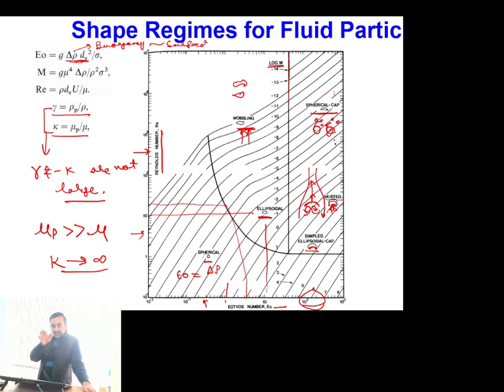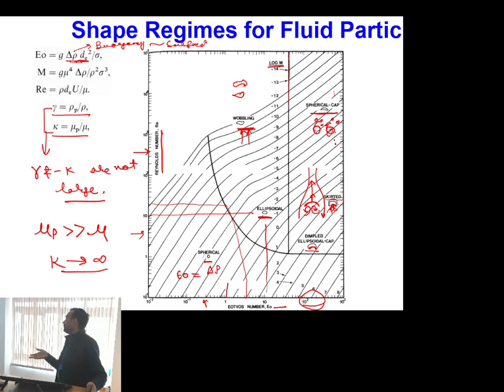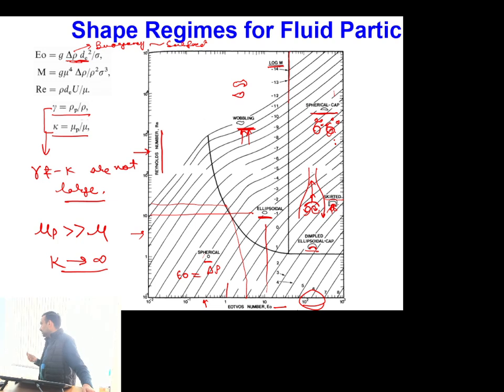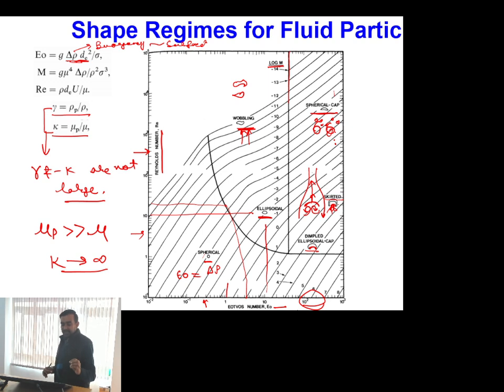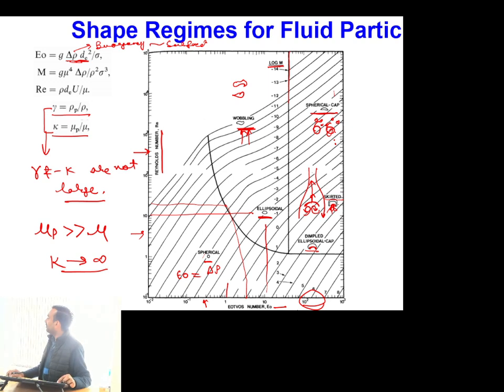And after that, again we are comparing the Reynolds number, which gives the relative combination between the inertia and viscous dissipation. So if inertia is high, corresponding to that, the dissipative effect will be less. So once dissipative effect is less, then oscillatory effects because of the inertia change will be large. Okay. And another point I told you that this particular plot is only applicable for finite values of gamma and